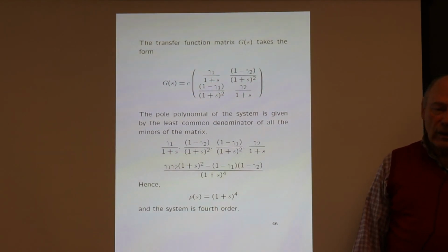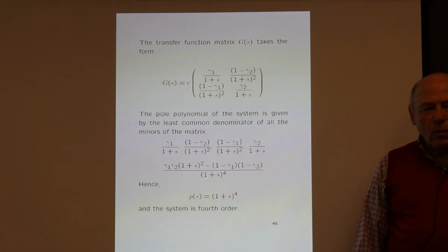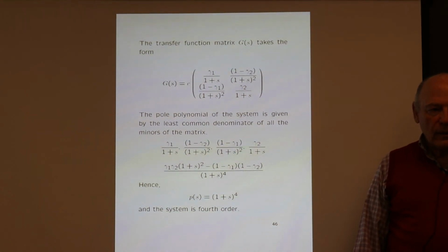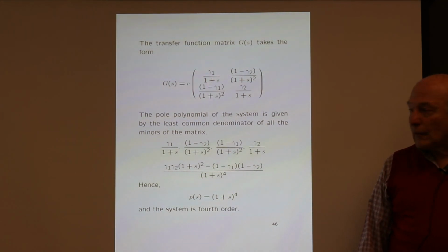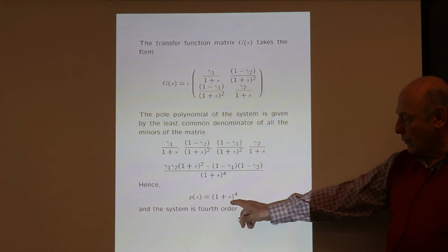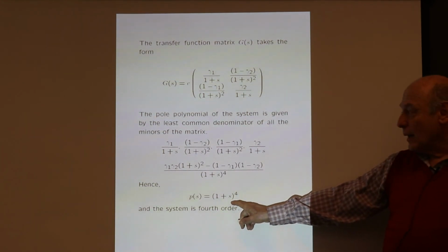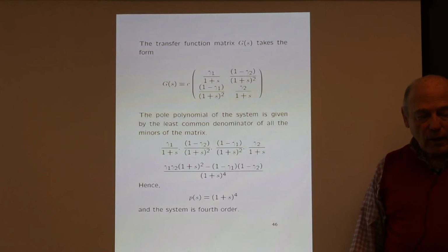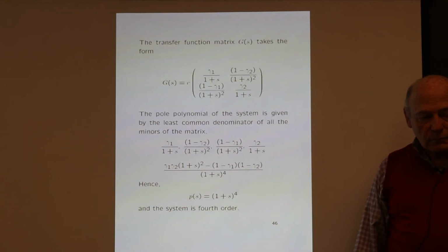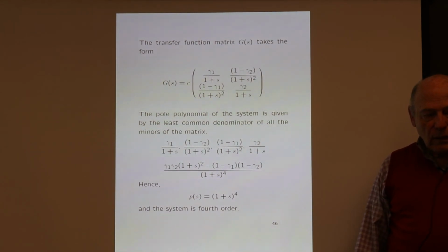So from each device you should be able to tell what the poles are, at least. Well, maybe. The poles come from 4 different tanks. Yeah. So if each tank has a different time constant, you have 4 different poles. Yeah, there is no influence of the gamma parameters in the poles. Right. But there is an influence of the gamma parameters in the zeros. So what are you saying? You don't have to look at the matrix. You just look at each device. You see what the pole is.